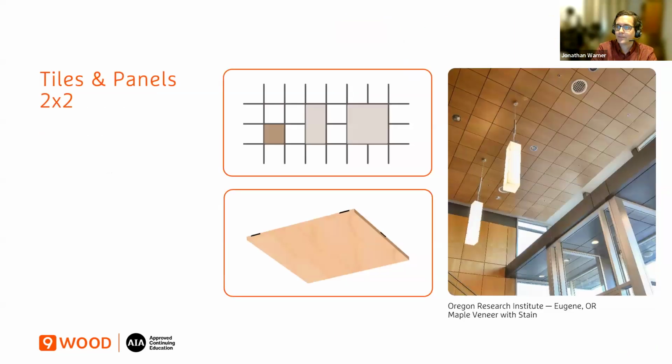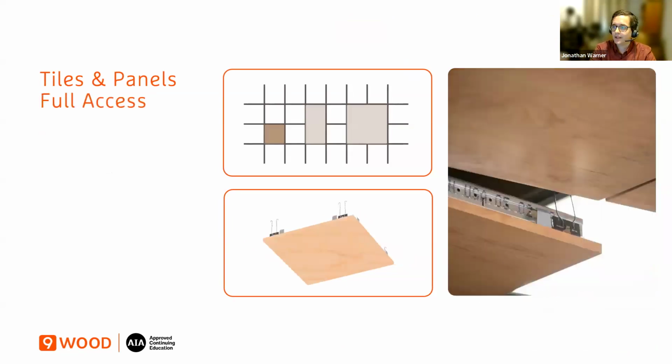And so this actually highlights what I showed earlier. That's a lay-in system, but it's not going to be seismic compliant. It will require additional hardware to go in that. And this shows more of a full access system. This is actually a tension flange system. And so a single person access, they can disengage it and maintenance can get up there, right? And make sure you have the right system you need for a project, and also that it ultimately delivers.